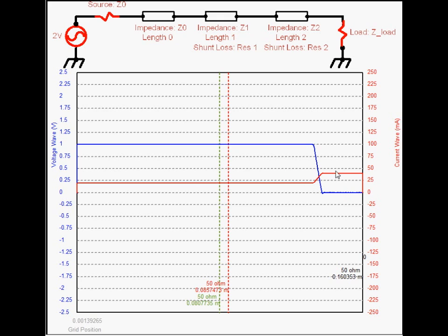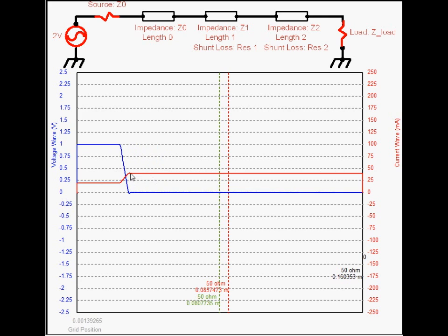And we have now 40 milliamps, because we have the 20 milliamps, and then we have a positive current wave that's summing with that, so 40 milliamps coming down. Now, at the source, we still have no idea what happened at the termination until about 10 nanoseconds later, when the voltage wave manages, the reflection bounces, hits again.